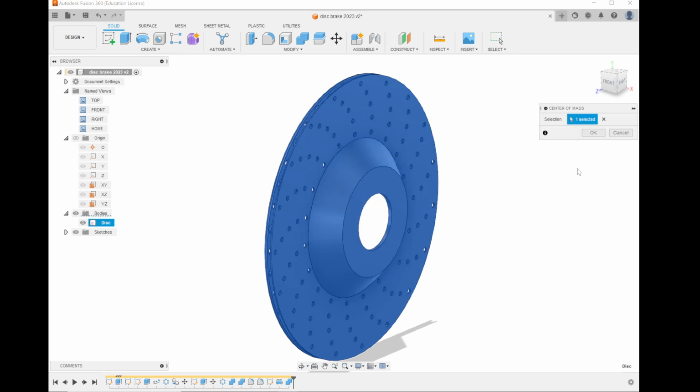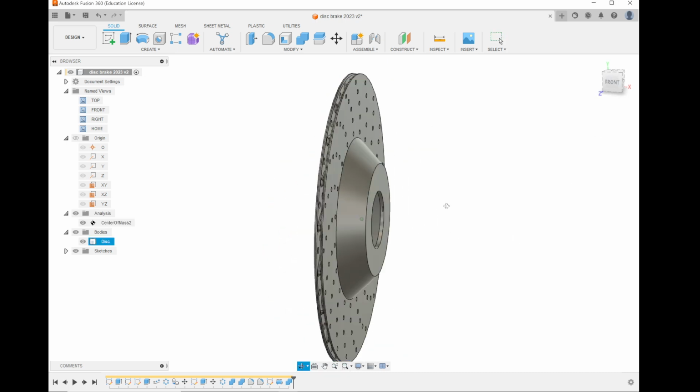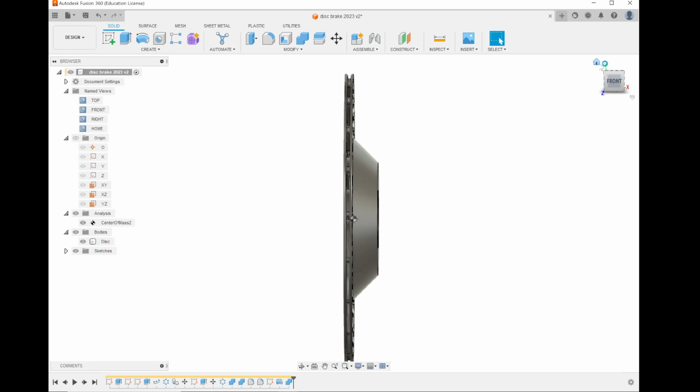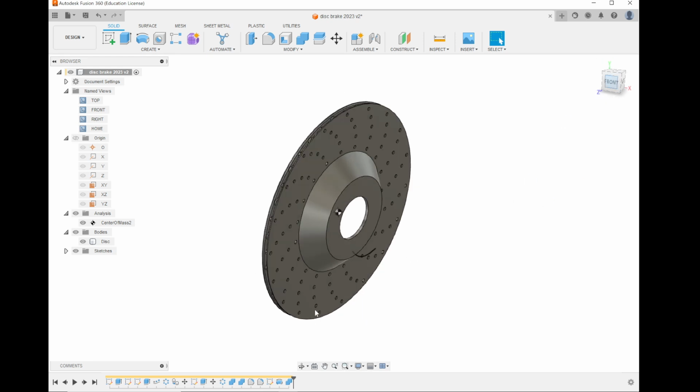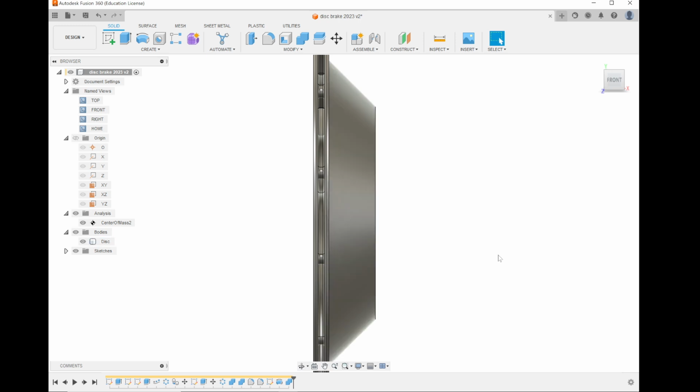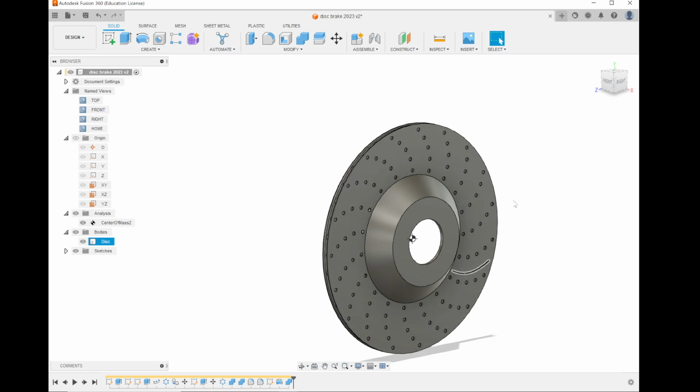That work? Okay, so select it over here. It's all selected. I press OK, and now the center of mass is now there. So we can use it in our design to find out where the center of mass of an object is. That would be kind of difficult to do by hand. You could do it. And I think you can combine multiple bodies in the center of mass, which is relevant if you have things of different density. You could find that out.